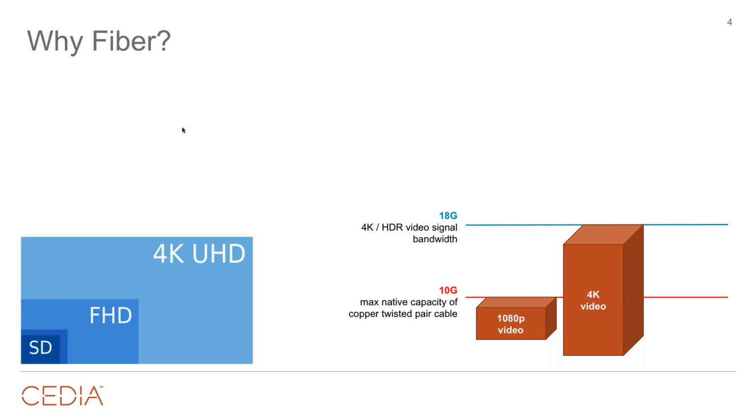Now, one of the issues that we're seeing is 4K video, and anybody who's doing these residential installations where the latest and greatest displays are being deployed, we know that 4K 4:4:4 HDR can exceed that 10 gig spec. Now, what happens if we're exceeding that 10 gig spec? And actually, HDR, these 4K 4:4:4 signals, can go all the way up to 18 gig.